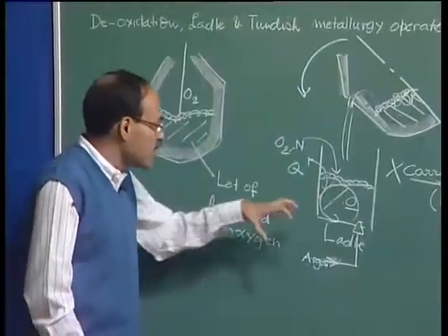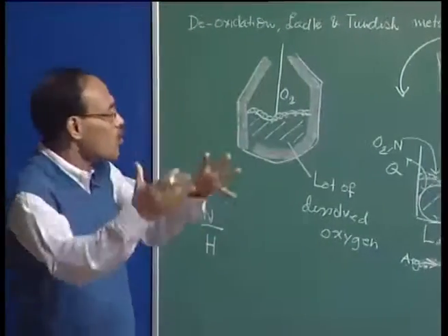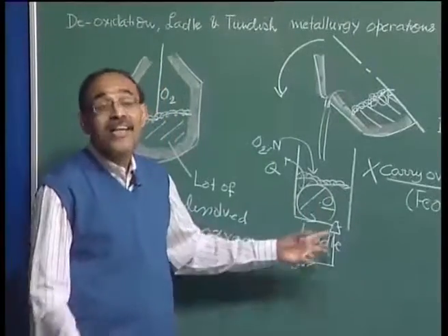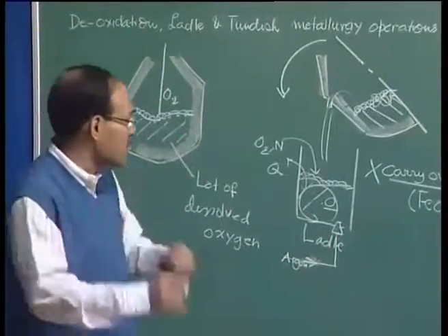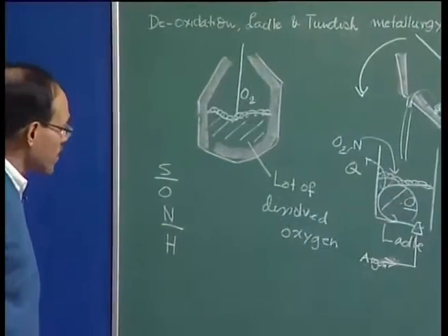So, to facilitate various steelmaking reactions, or moving of heat from one point to another, we have to have some amount of stirring present, and gas stirring, by the way, is the cheapest mode of ensuring stirring in a high temperature system, which is at 1600 degree centigrade.